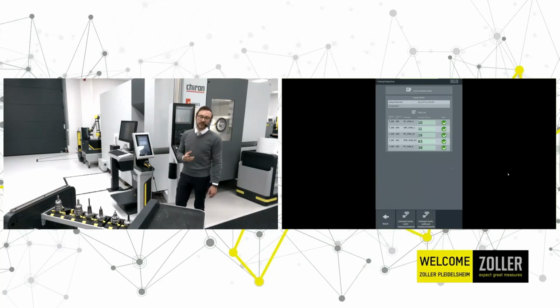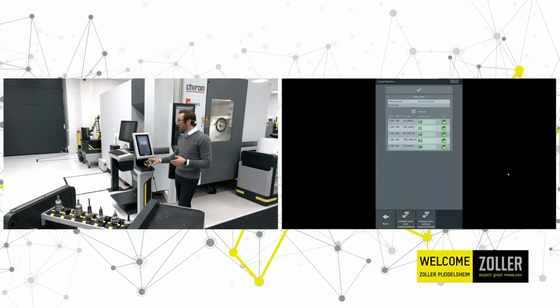So this is a huge benefit for you, because the tools which still have lifetime, we unload them with the measurements. So this means all we have to do afterwards is take this tool and store it back. They are already ready for the next order, because they have lifetime, they are measured, and all is prepared. So you will minimize your setup time for the next order as well. So unload the tools with the measurements because of the benefits I have explained. So the tools are ready for the next order.